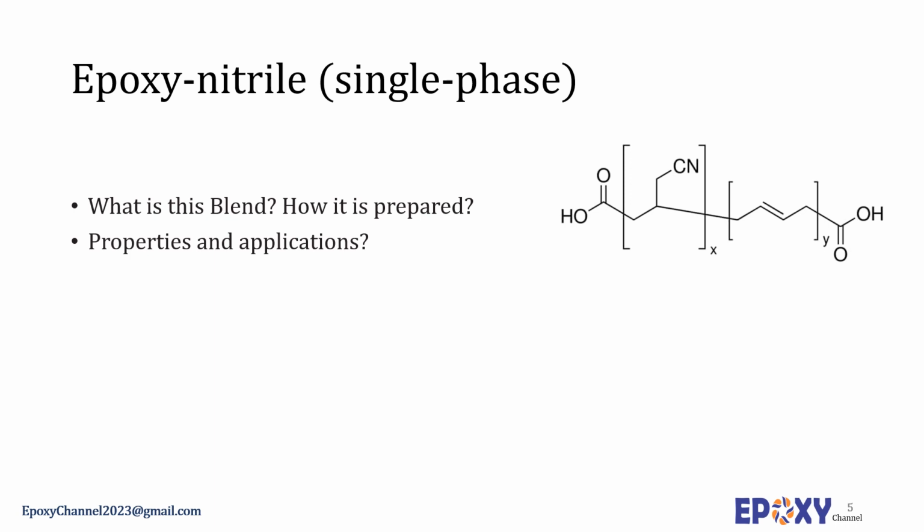As a result, nitrile modified epoxy adhesives have found applications in bonding airframe structures and other applications where a combination of high tensile strain with peel and impact resistance is required. Nitrile elastomers offer a unique blend of properties.